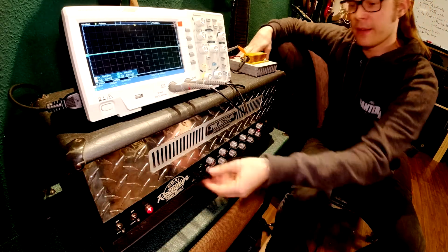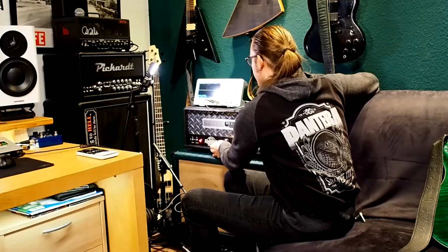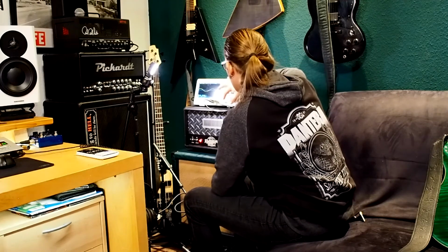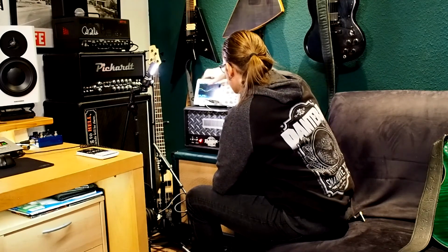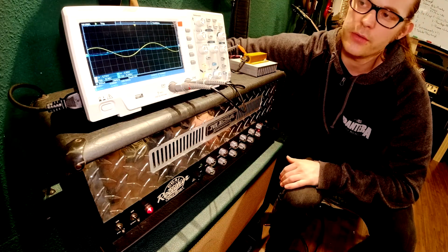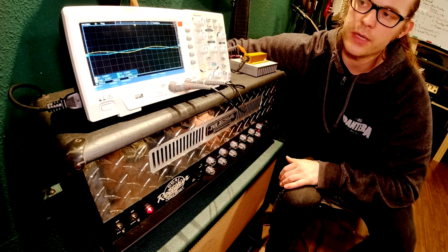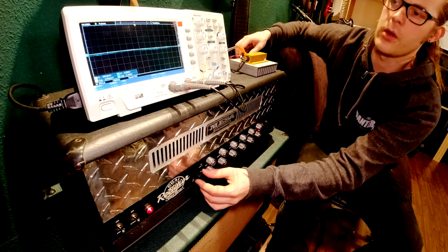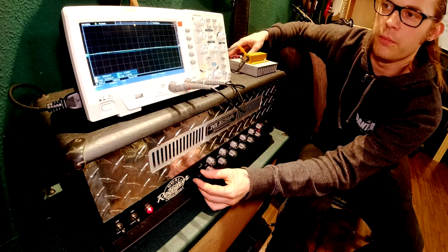Let's power on the amp and let's get the volume up. And here you can see the sine wave. Okay, channel 1 is yellow. This is 10 volts per division. I have the slave output totally turned up, so now I turn it down. We have seen the sine wave, we know it is there, and now we are concentrating on the blue channel,